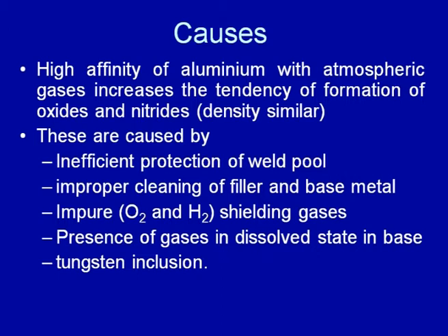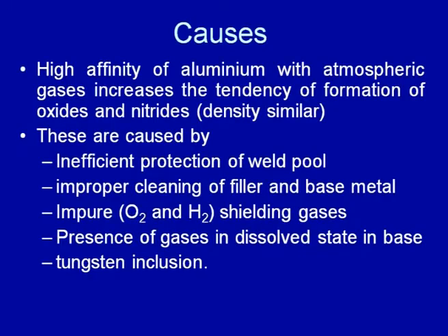If these have not been cleaned properly, then the impurities may be in the form of hydrocarbons, which will offer hydrogen and carbon during the welding on decomposition. And then, if the shielding gas itself is impure, it will provide oxygen and hydrogen, which will react with the aluminum to form aluminum oxide, and hydrogen will increase hydrogen induced cracking and hydrogen induced porosity in the aluminum weld.